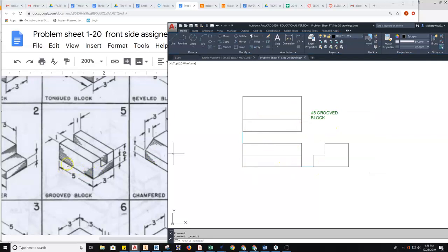And now I want to change this view so it looks like the front, top, and right of number 5. This line would not exist. On the front view, I cannot see any other object here. From the top view, as I look down, I'm going to see 3 surfaces. One surface and this back second surface are going to be at the same plane. The notch that's running through the part would still be visible, but I would not see that it is further